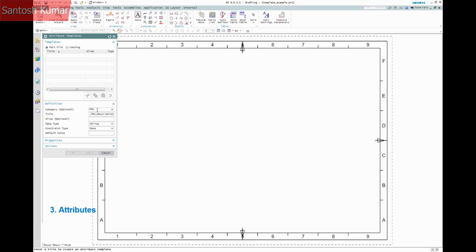The db_dwg_template tells NX that the attribute is to be linked to the named attribute in the model part file. In this example, I want to link to the attribute I created for the description. And to the mass prop mass 1 for the mass value.